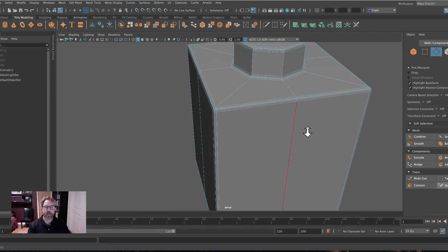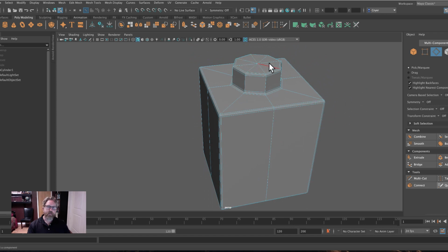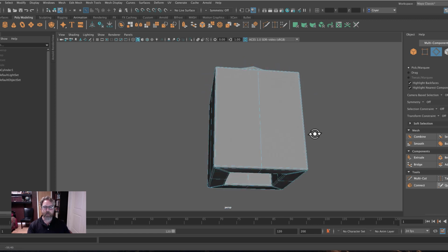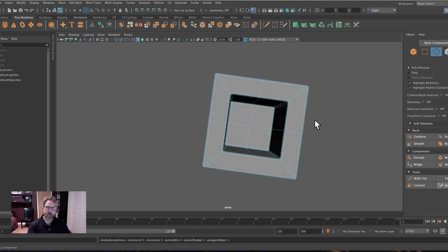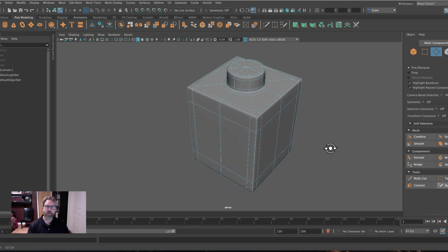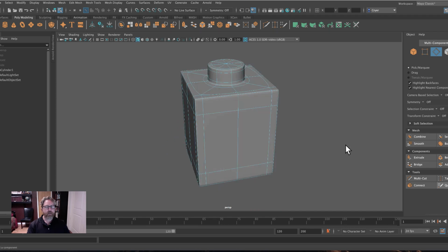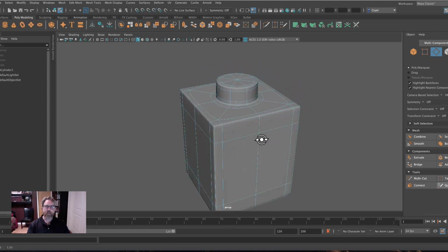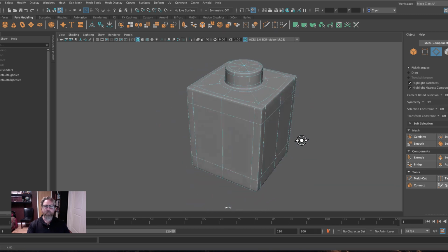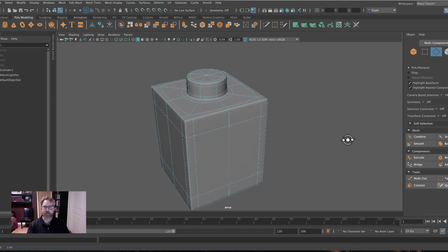Here we've got 4-sided. And then we've got tris on the top, right? A 3-sided face is referred to as a tri, but once we subdivide it, it will create quads up there. So we have nice tight, right? Here's 1. We can hit 3 as a preview for the subdivision. And that all looks good. If it didn't, again, if you missed an edge or you accidentally selected an edge that we didn't want, undo back or reopen and just give it a second shot.